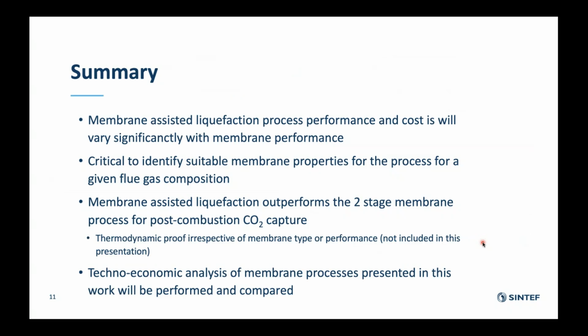Okay, so with that, we come to the last slide and the summary. The membrane-assisted liquefaction performance and cost will vary significantly with membrane performance. It is critical to identify suitable membrane properties for the process for a given flue gas composition, because depending on the flue gas composition, the type of membrane which will be optimum will vary, as we've seen.